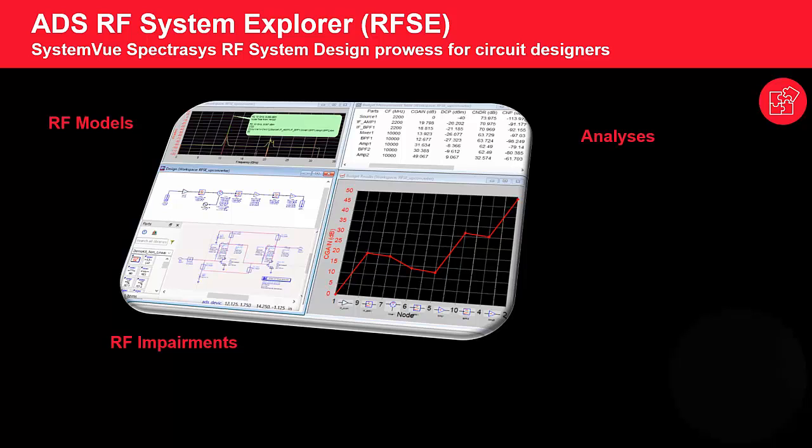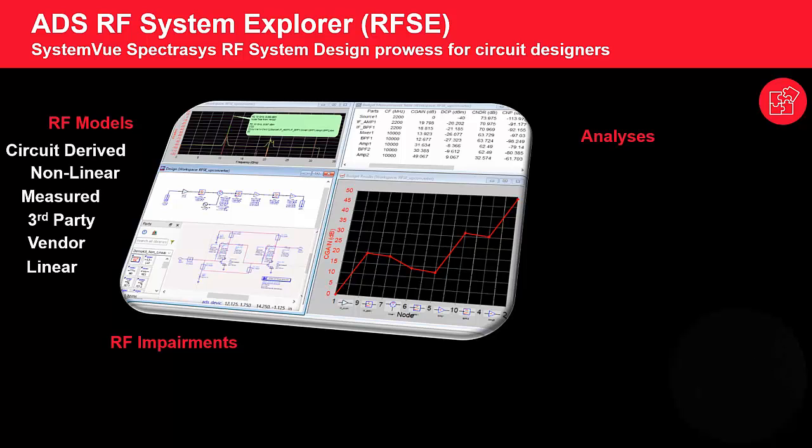So RFSE is launched from ADS and it has access to many of the RF system models that are in the SystemVue Spectrasys. It also has the ability to capture an RF system level representation of your circuit, for example, a power amplifier or a mixer, and then bring that into the RFSE environment to look at link budget analysis.